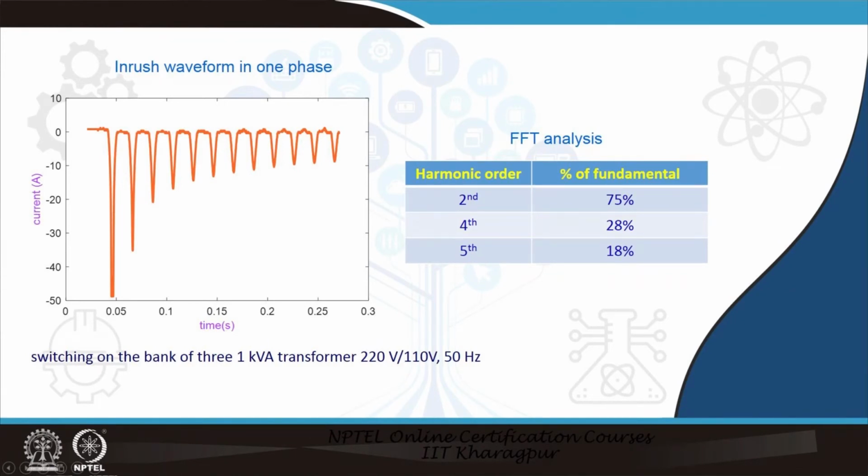Another situation in the differential relay issue is overfluxing, as already enumerated in the lectures. Whenever the voltage is higher, the inflow of current, similar to the inrush situations, becomes enormously high. It may also lead to operation of the differential relay, as the differential current will fall in the trip region and lead again to unnecessary tripping.